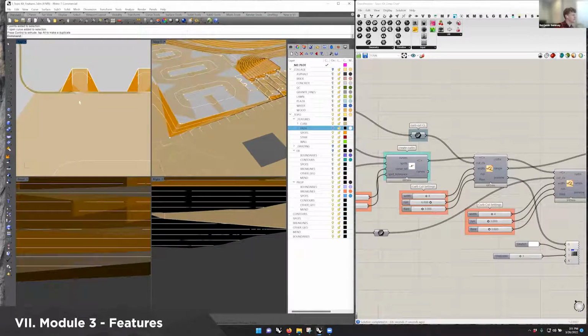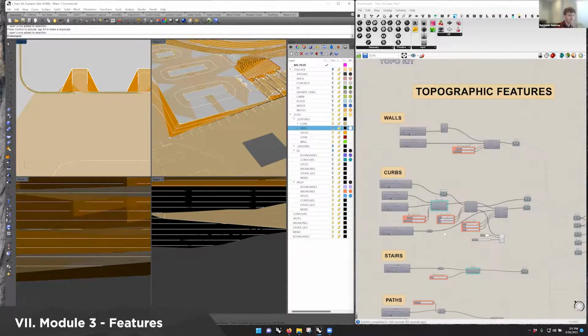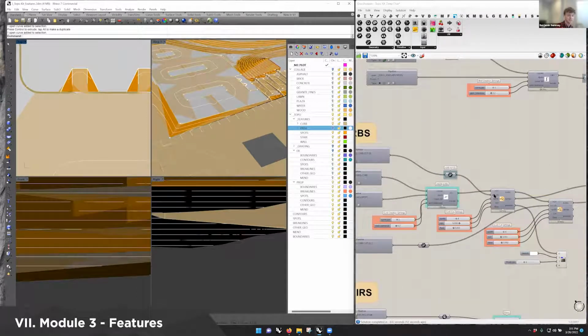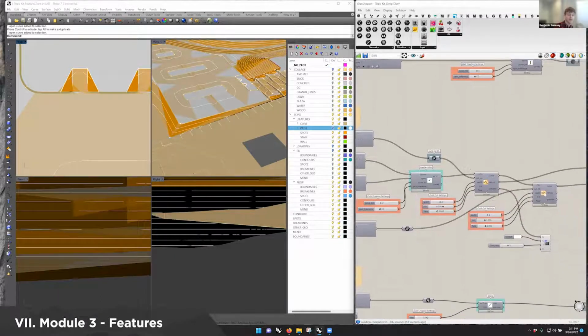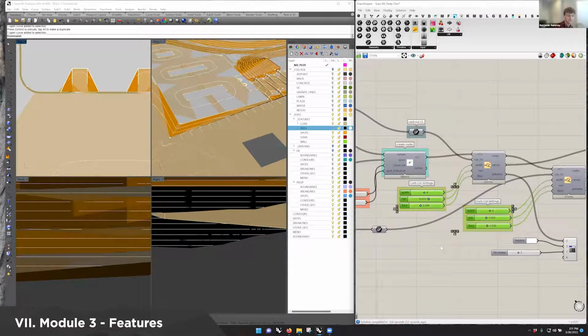I should probably turn off the areas. It just shifted my curb cut over. So you can just draw these lines anywhere along your site and shift them around, and add as many curb cut lines as you want to a single component, and it will process them all together for you. Again, the only reason you would need to have multiple, like I have here, is if you have different sets of parameters.